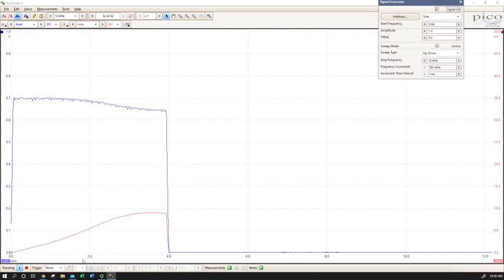So again, we are looking at kilohertz on the bottom. So we go from 0, 2 kilohertz, 4 kilohertz, 6, and we can see our red display is voltage drop over our series resistor, and it's got a peak somewhere between, say, 3 and maybe 5 or 6, and we can clearly see the corresponding trough in our full circuit voltage.